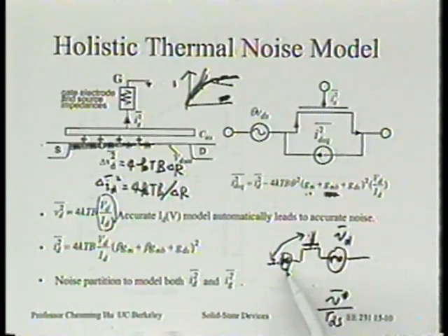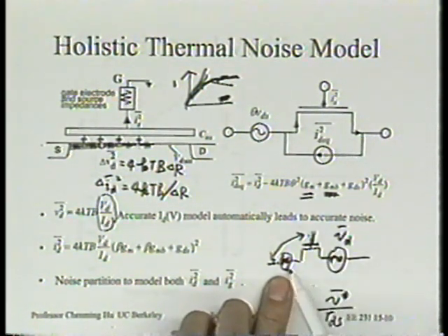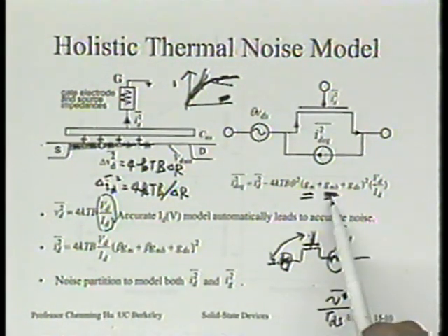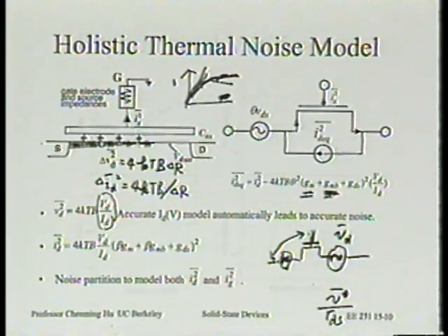By definition, it is going to be amplified by the front gate through GM and amplified by the back gate through GMB. I did not say GM and GMB are typically very similar in value. GMB is certainly expected to be smaller in value than GM because the front gate is thinner than the back gate. But in terms of the form, it should be identical.